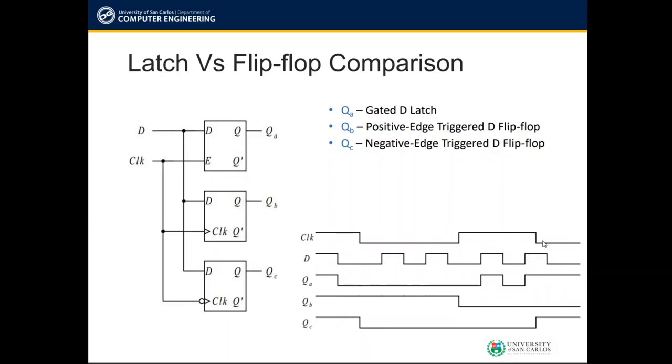And then this is now low, and that is now disabled. So even though this part here goes low, the output is steady because it was disabled. Whatever value of your D here doesn't affect your output because it is disabled from this part.